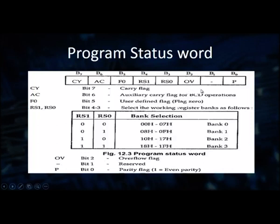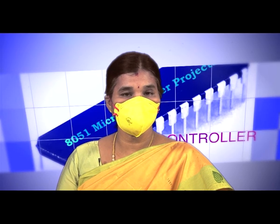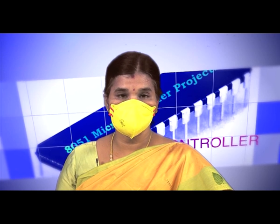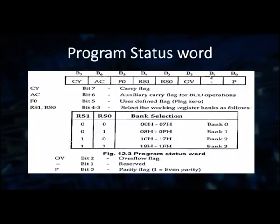Overflow means exceeding the size. Actually, we are adding two numbers which are 8 bits each, right. 8 bit plus 8 bit, and we expect the result also in 8 bits. Suppose the result goes into the 9th bit, then automatically this bit position becomes 1, which indicates it is exceeding the size, right. The overflow has occurred.